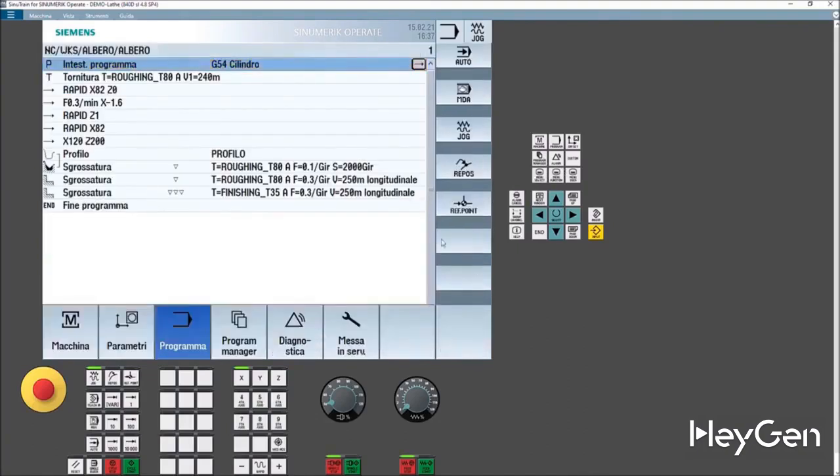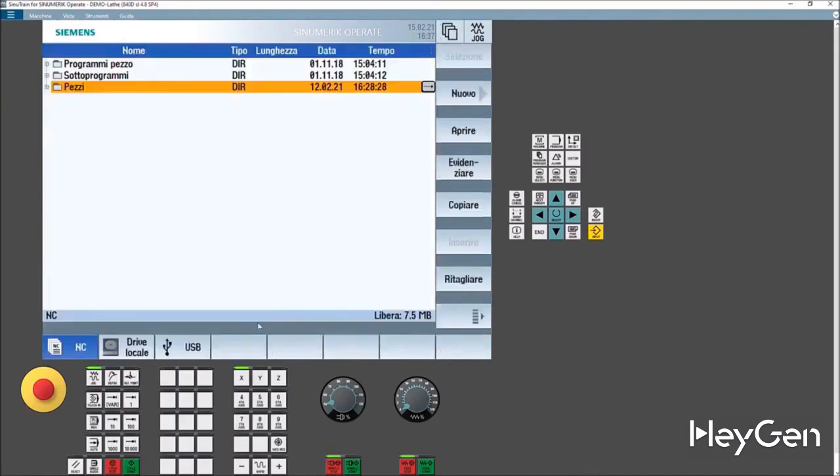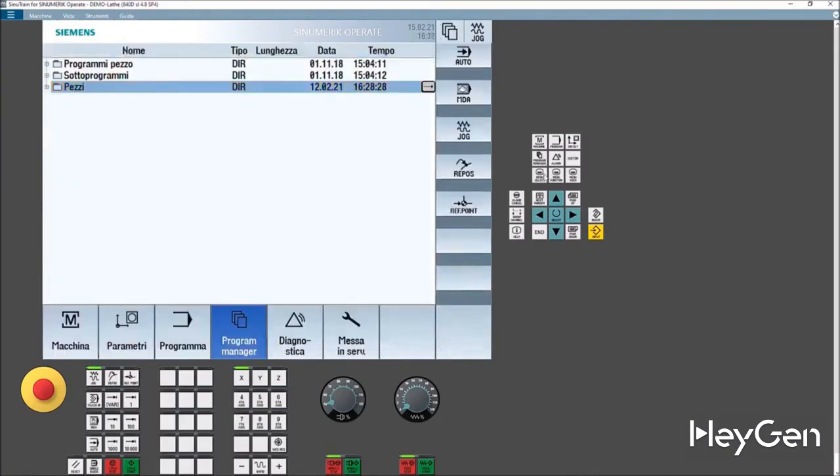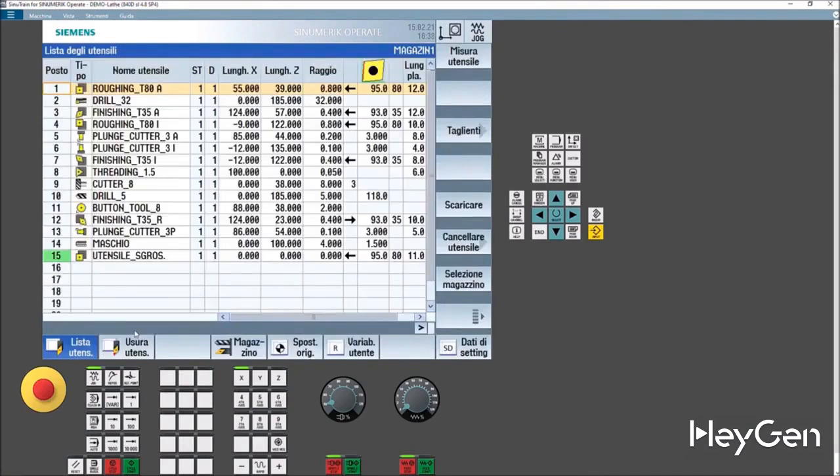The menu adds parameters to the tool list. Standard tools are preloaded. Tool names and images are visible. It shows 80 degrees as the insert angle. The software adjusts graphically when setting the insert angle to 55. Changing the tool holder moves the insert. It provides insert dimensions, spindle rotation, and coolant use, depending on the machine.